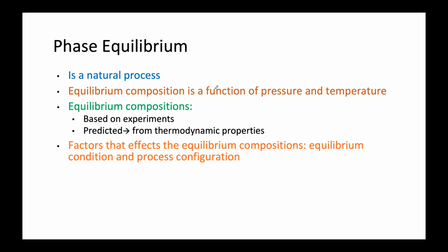For example, gas will always flow upwards. So when we separate gas, we just let the gas vaporize, and on top of the distillation column we install a condenser. So all the vapor will be condensed, and then we can collect it as a liquid.